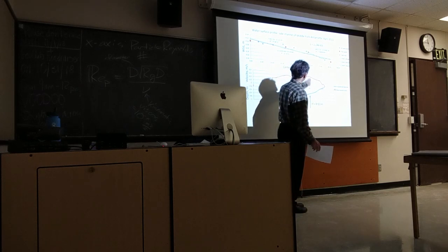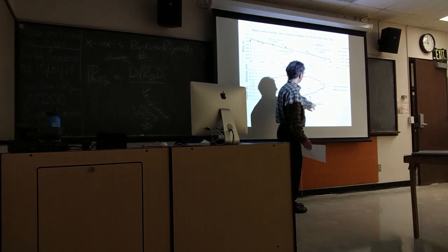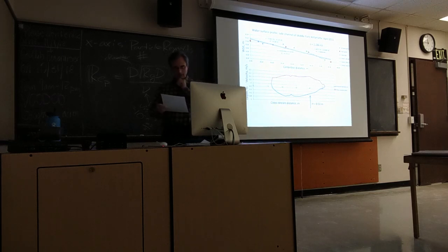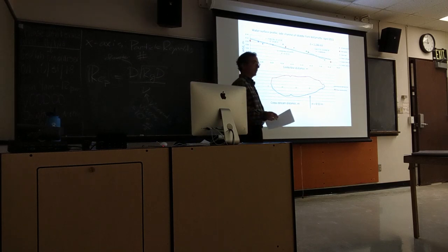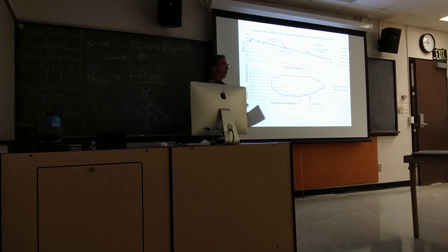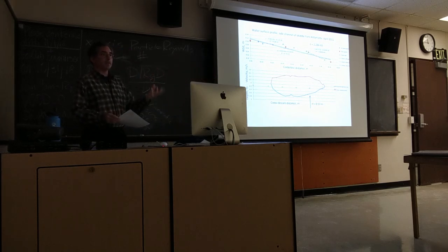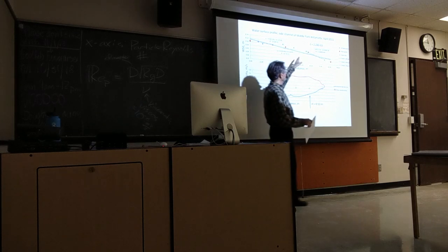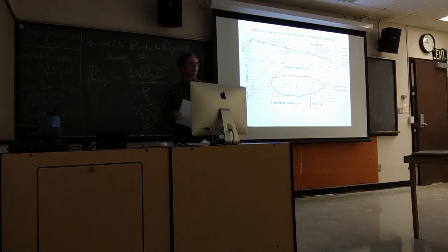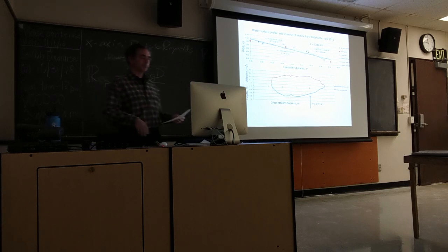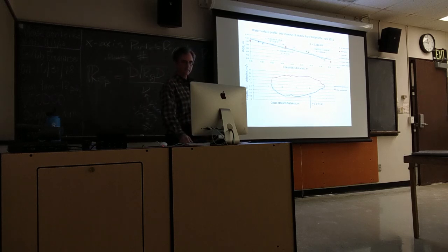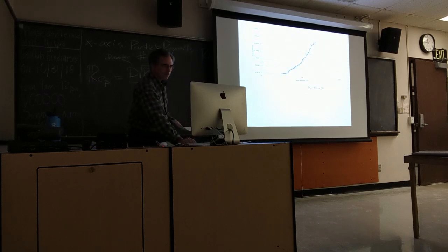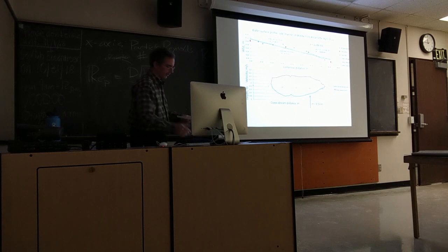This is where those velocity data were collected, where the depth is 0.53 meters. So if I use that tau equals density times gravity times depth times slope, I come up with a shear stress of 11.8 pascals. 11.8 versus 12.5 is not perfect, but it's okay. Considering how fuzzy everything is and how difficult it is to measure a good water surface slope that small, it's probably pretty decent.